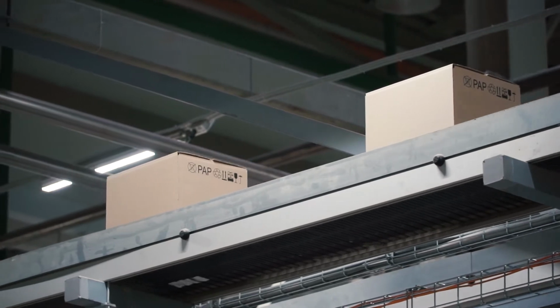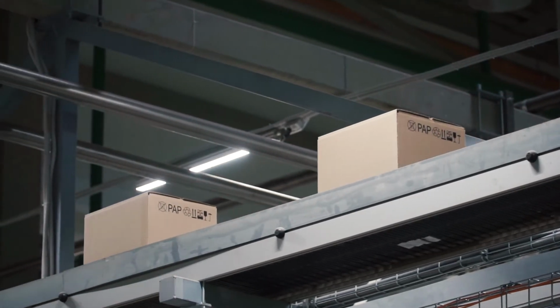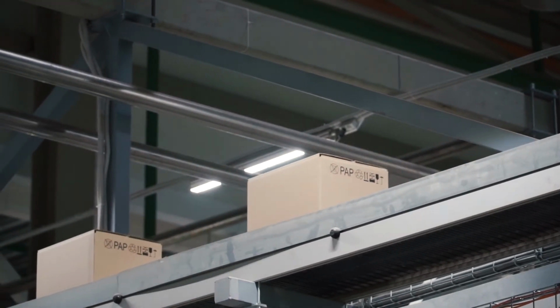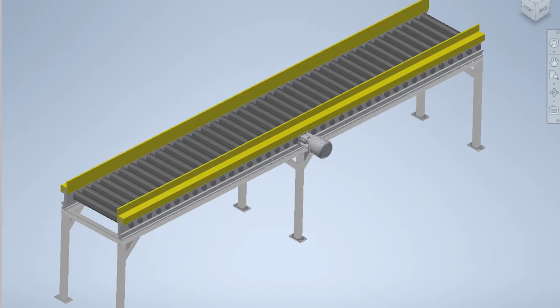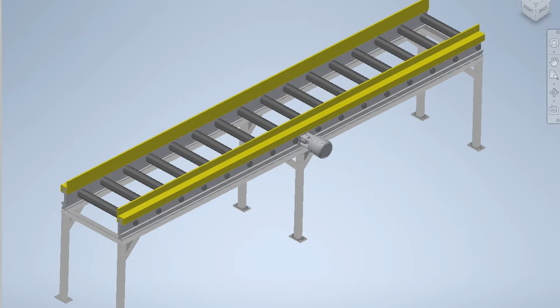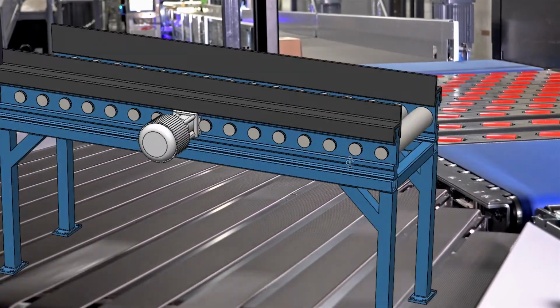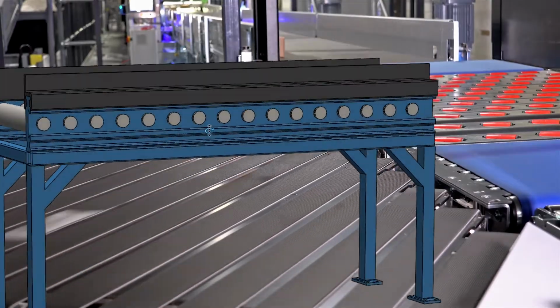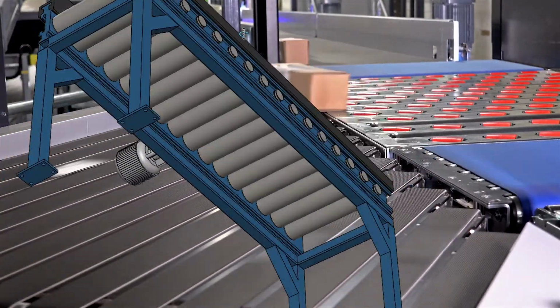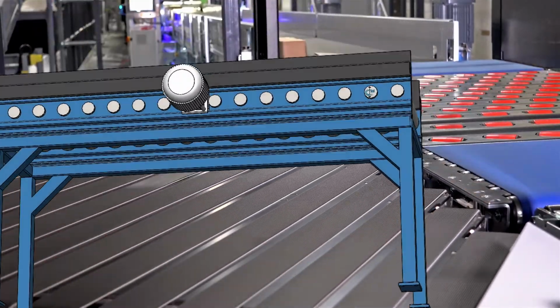Supported package sizing is something that the customers always ask for. But in order to support the right maximum sizes of the packages, size of rollers and the distance between them is important, as well as the width of the conveyor. So, even for this rather simple product, there are a lot of parameters to keep track of when making a conveyor design for each customer.